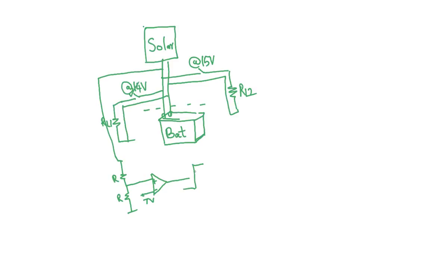Now what happens if I turn this switch on? I connect a large load, basically a small resistance across the battery, so that the current from here will now go there and not go into your battery. But generally what happens is that the battery voltage was clearly below 14 volts so far, so it was charging slowly, and it has reached 14 volts now.